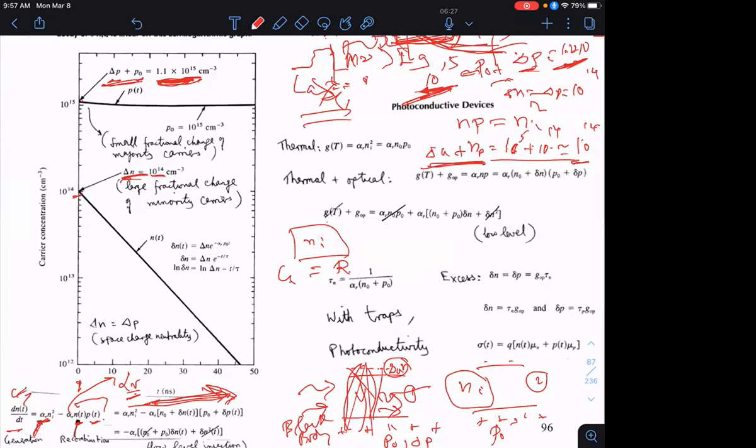All right. So what is going to be the recombination? Is this just the rate at which the electrons are filling holes and new holes are opening up? Exactly. So it's a dynamic process, right? So this semiconductor bar has a valence band and a conduction band, right? The black body photons are being absorbed, creating electrons and holes, but they just don't stay there.